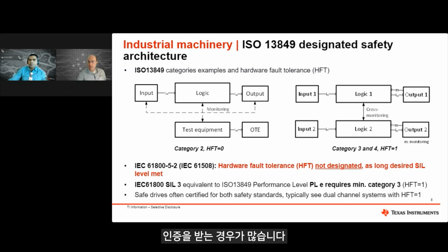Failure modes can be found in the relevant industrial and automotive standards as listed on this slide, or, for example, also in handbooks from Exida. Now, since we want to certify also against the industrial machinery standard ISO 13849, what about failure modes for capacitive isolators? The ISO 13849-2 from 2012 does only mention optical isolators. Well, we go to one of the other safety standards.